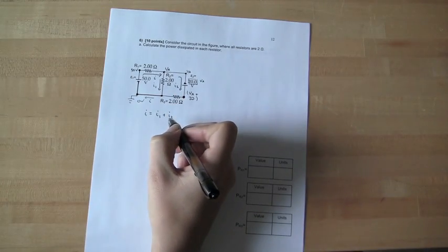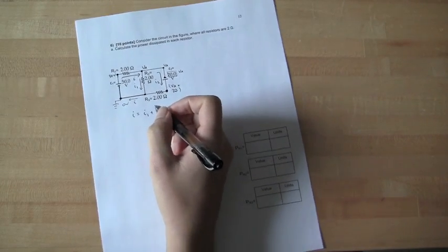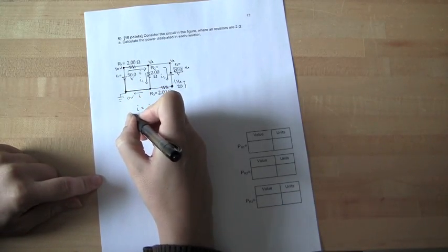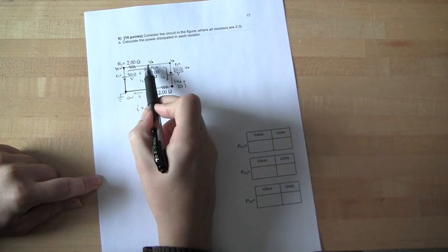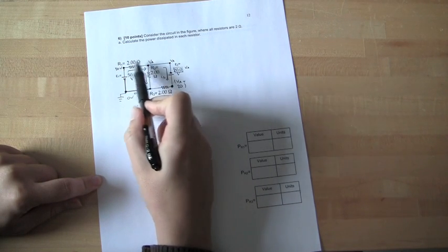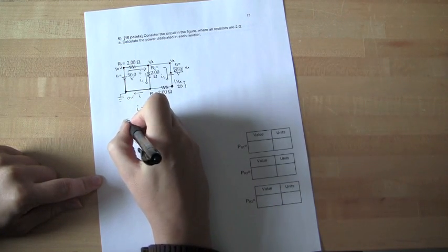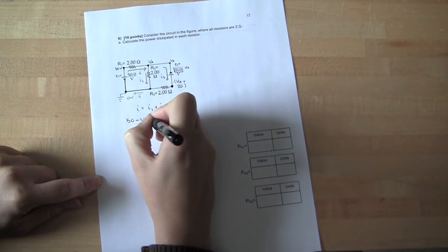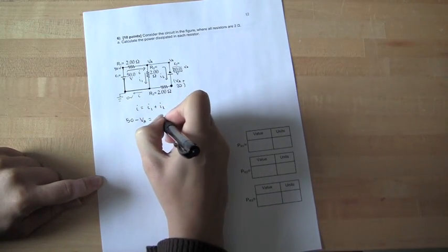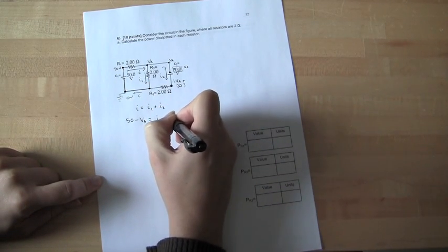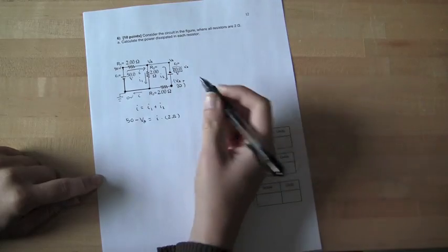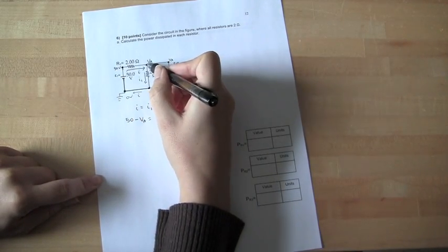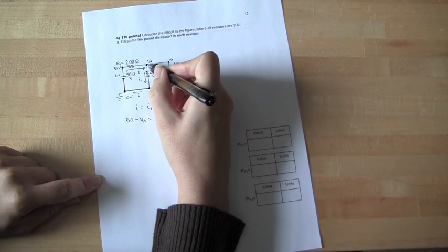We also know that you can write some equations for the relationships between these voltages. So there's 50 volts minus VA dropped across this resistor here. So the voltage across this resistor, 50 minus VA, is the current through that resistor, which is our current I, times the resistance, which is 2 ohms. Now for this resistor, we have just a voltage dropped of VA.